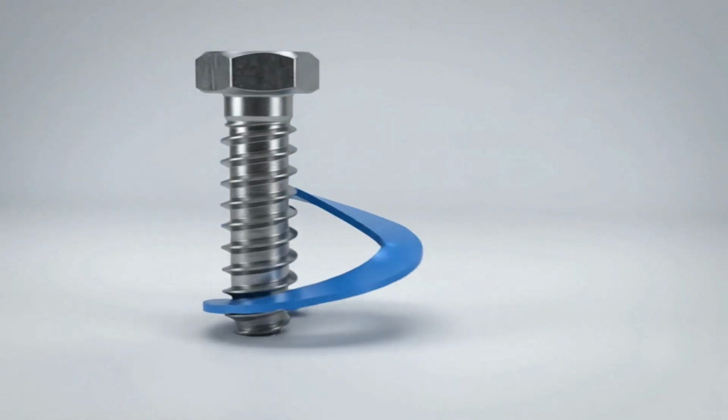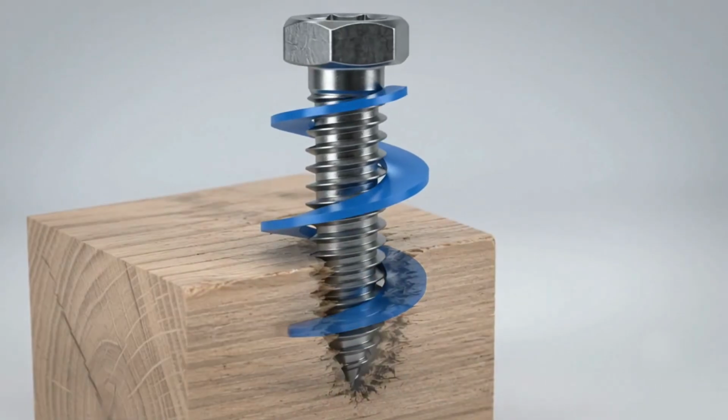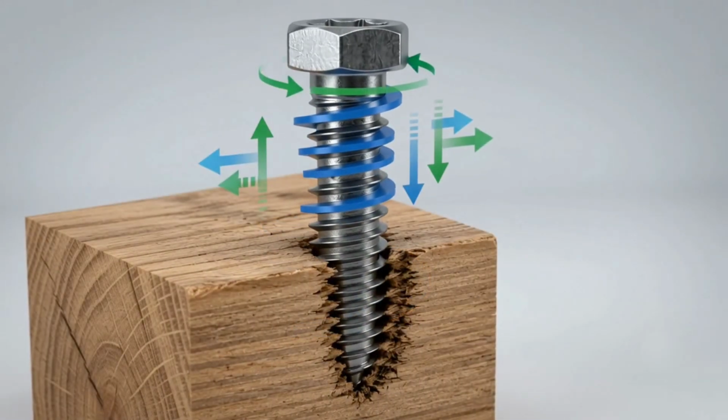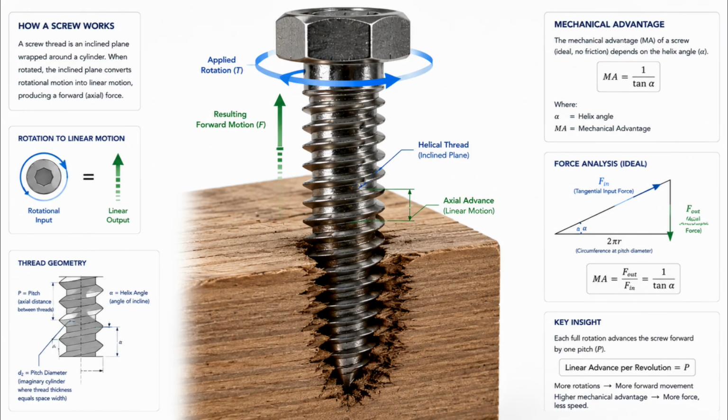A smaller pitch increases mechanical advantage because more rotations are required to move the load the same distance. This allows screws to generate large forces from relatively small turning efforts. The screw is one of the most efficient force-multiplying simple machines and is widely used in fastening systems, presses, jacks, and precision engineering devices.